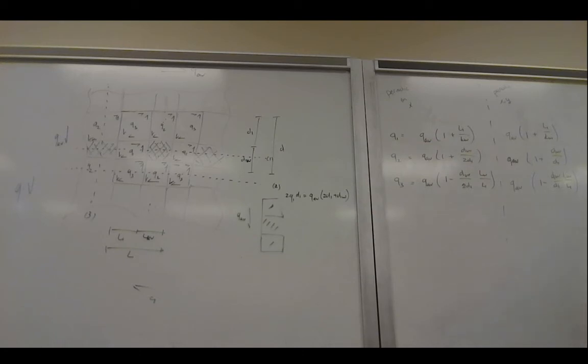Yes. Q average is just the average of all the four corners or something? No, Q average is the far field shear flow. So you have to think about cutout.